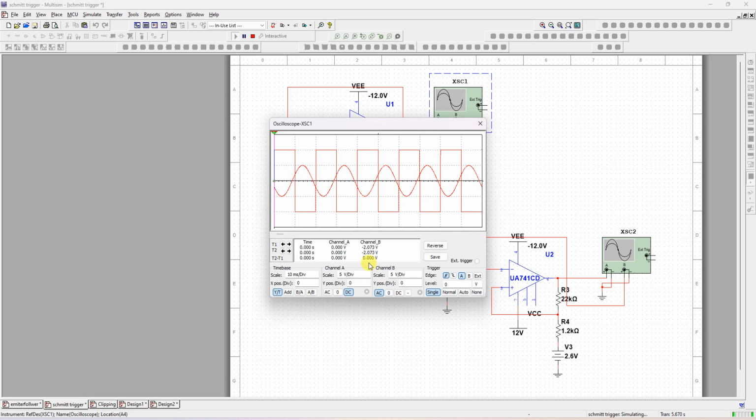Now if you have input, we have already seen the zero crossing detector. Whenever input crosses 0, output changes. Now instead of that, we are having two reference voltages, UTP and LTP. Output is actually changing whenever input wave crosses plus 2 volts. Whenever input crosses minus 2 volts, output changes from one state to another state. And hysteresis curve is obtained by input versus output.